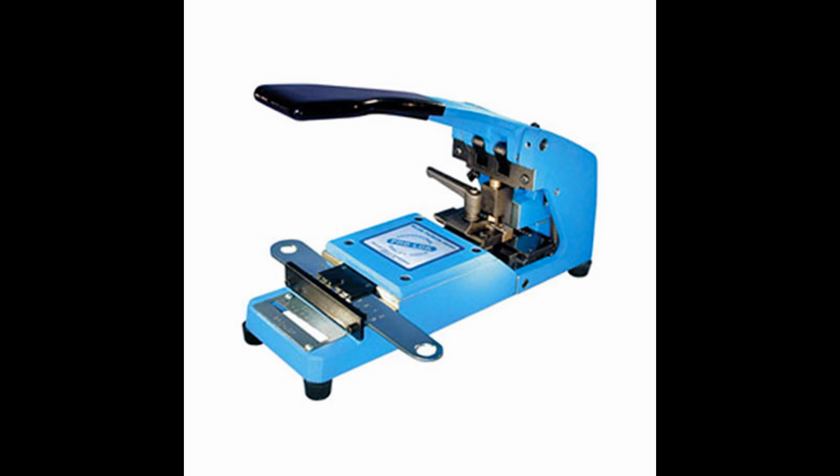So the Hager keying system shares in common with the Best A2 system all of the depths. The thing that's different between Hager and Best is the spacing. The spacing on Best is 150 thousandths and Hager's is 140 thousandths. So the answer is you could simply use any Best A2 key gauge to gauge your keys.